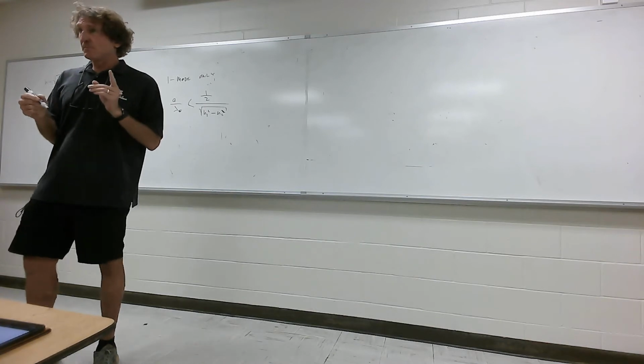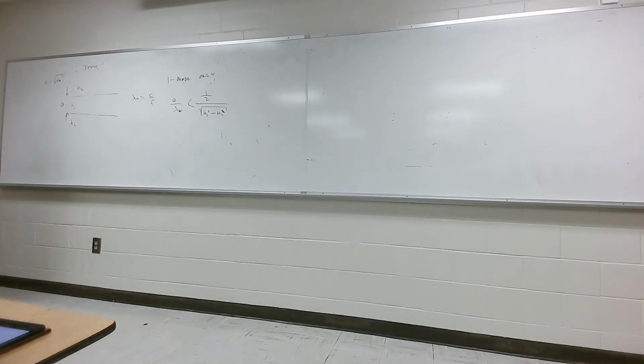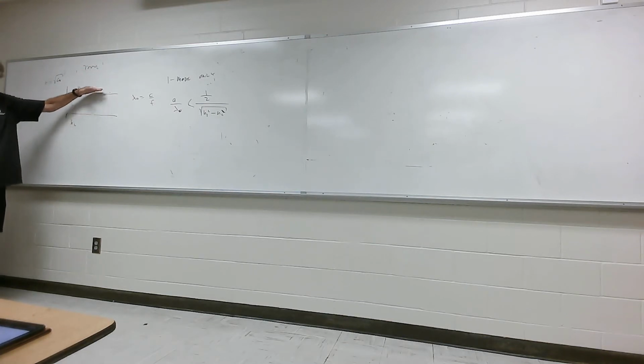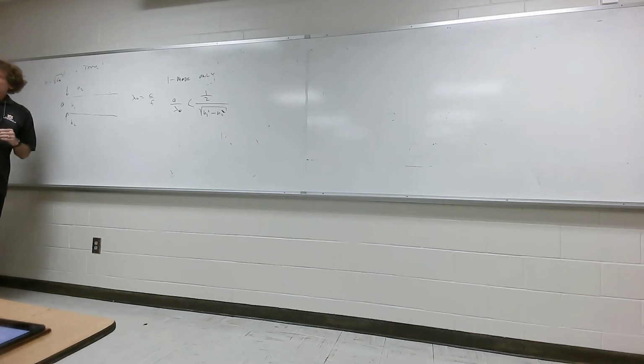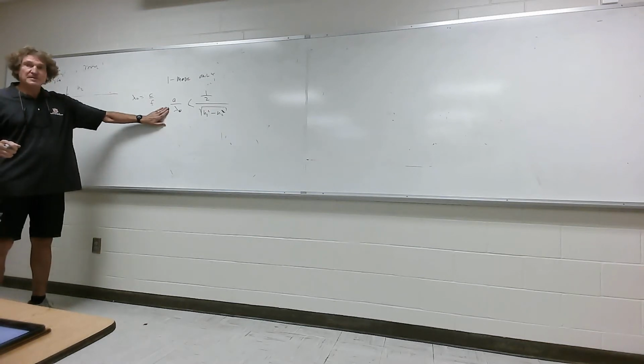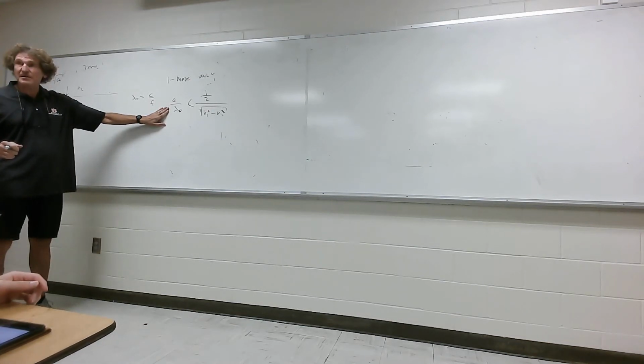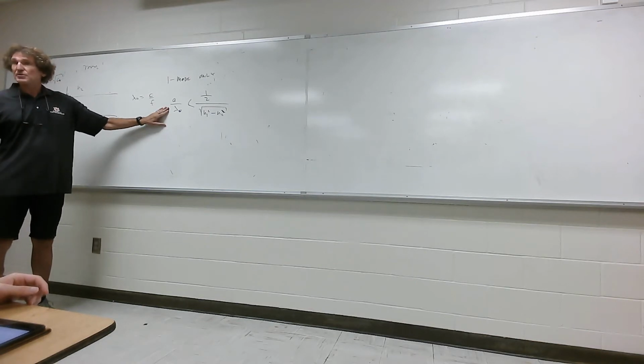So, for single mode, after all said and done with those equations, you get the solutions to the del squared equation here and here, and you match the boundaries with the solution in here, and you get these trajectories. Basically, they're tangent functions. You find the solutions where they intersect. After all that's said and done, they come out at the end of this and say, if you only want one mode, which you do, you have to meet this criteria. And if you meet that criteria, you check the boxes. That's it. Now, there's a lot more to this, but it's much more advanced, and we can't get into it. But that's really it. Do you follow me on this, class?